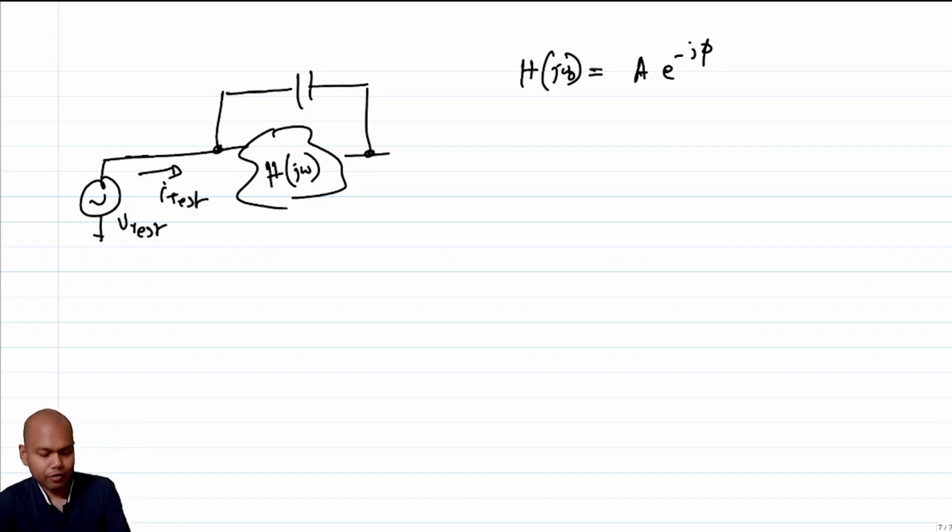So at a particular frequency, if I change the frequency, A might change, phi might change. I'm not talking about all frequencies, because ultimately we understand that one good thing about our RF systems is that they can be narrow band, right? They can be concentrated within a certain band, and we don't care what is happening at the other bands as much. So if I can get a real impedance using inductors and capacitors or imaginary elements across a very small band, I'm good, right? That's the assumption, that's the hope.